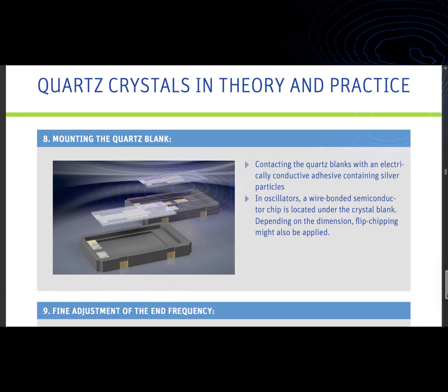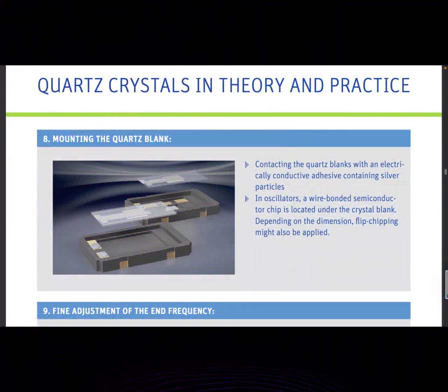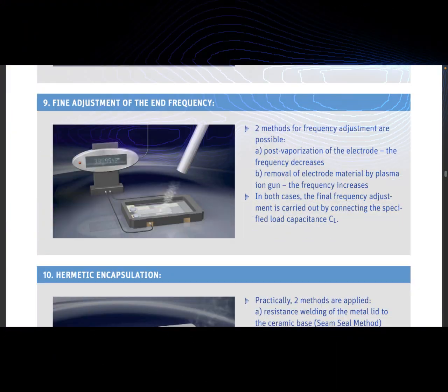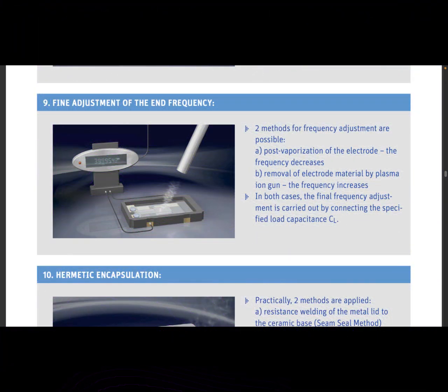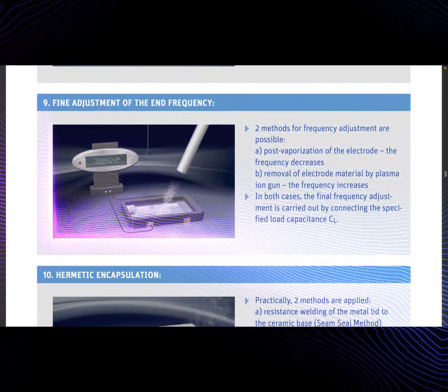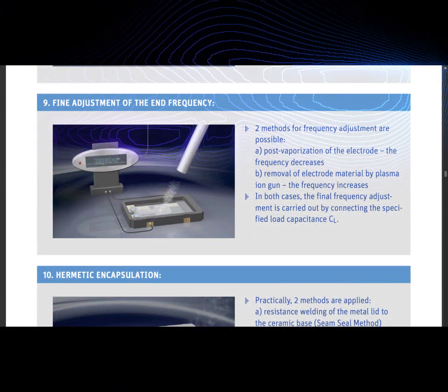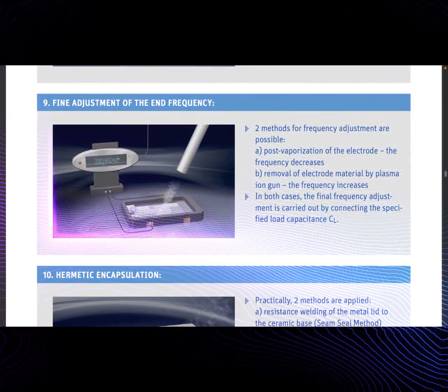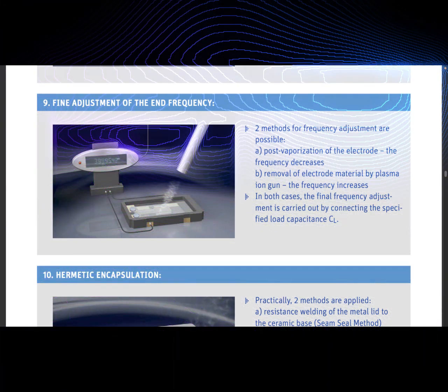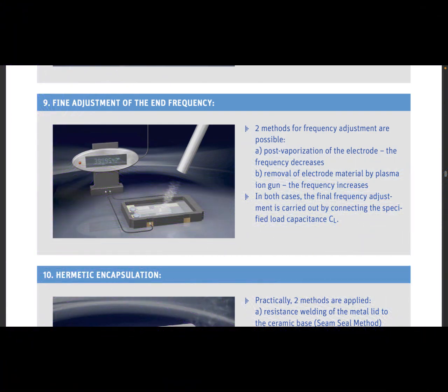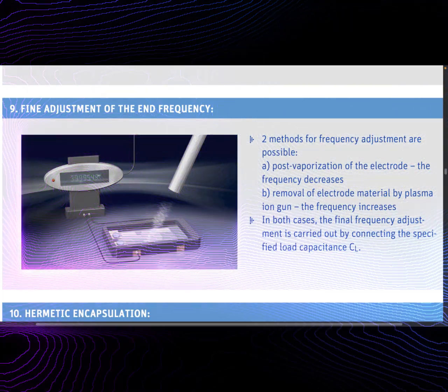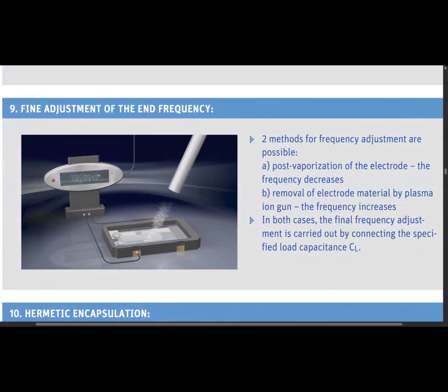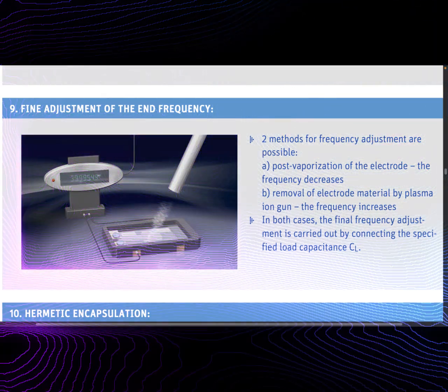Load capacitance. The external load capacitance must match the specified crystal to ensure the correct frequency of oscillation. A higher external load capacitance decreases the negative resistance of the oscillator, which increases the startup time and the load. If the load capacitance is too low, it can make the oscillator frequency more sensitive to stray capacitances and board layout.